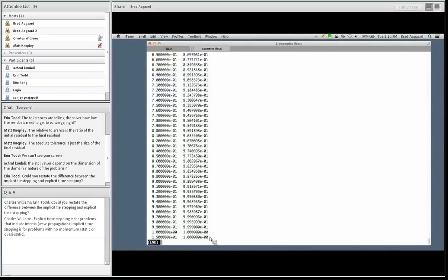So my time history file did not need to use a uniform time step or time sampling. Pylith is smart enough to go in and do linear interpolation. And so because I had sort of a smooth onset over 1 second, I did a fine sampling of that smooth onset. But once I reached that steady state value of 1, I knew there was no reason to have additional points in my time history file. So I can use uneven sampling of points, and Pylith will just interpolate.